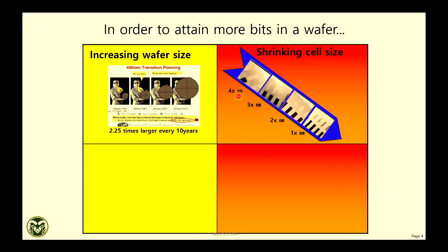So that's what 4X means, 40 nanometer or 40-something nanometer. 3X means 32 nanometer or 30-something nanometer. 2X, 1X. So that's how the technology has been shrinking for two-dimensional NAND memory, which is very similar to your CMOS process, CMOS technology scaling, right? At what CMOS technology are we right now? Around 5 nanometer, right? That's where TSMC makes. But 5 nanometer doesn't mean exactly the geometric dimension is 5. The geometric dimension is a little bit longer. But yeah, that's the CMOS scaling, and 2D NAND was also following that.